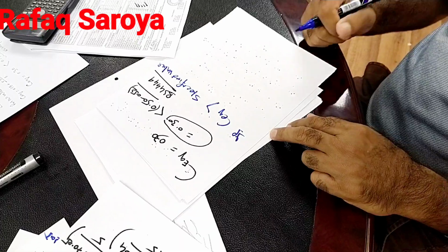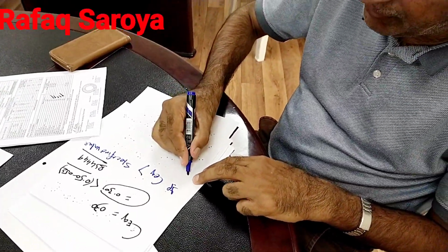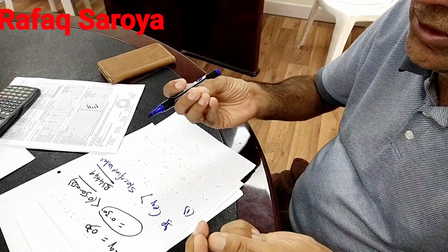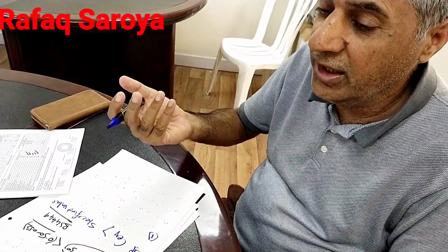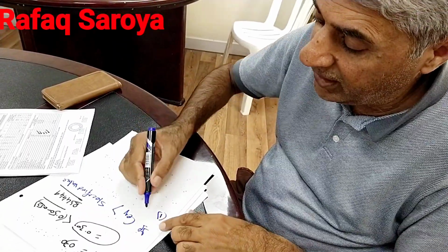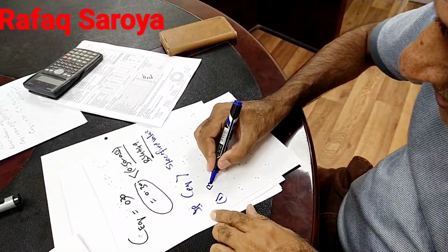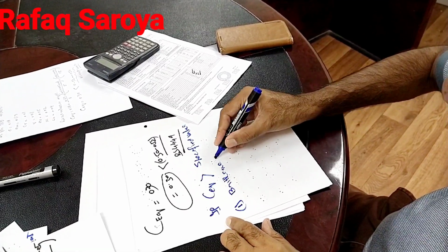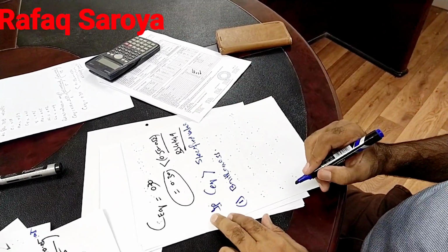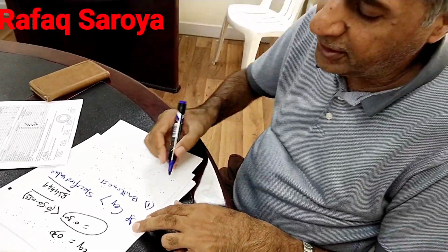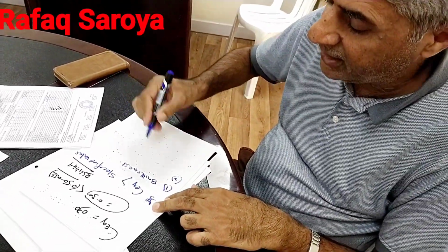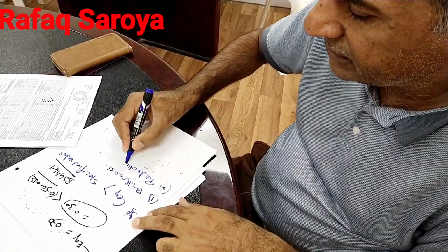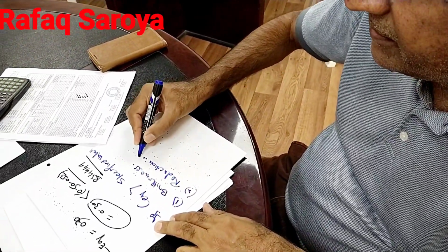Which characteristics are going to change? First of all, it will not be low carbon because the carbon amount has increased. If it is not low carbon, it is going to get brittleness, one very important property. Second, reduction in weldability.